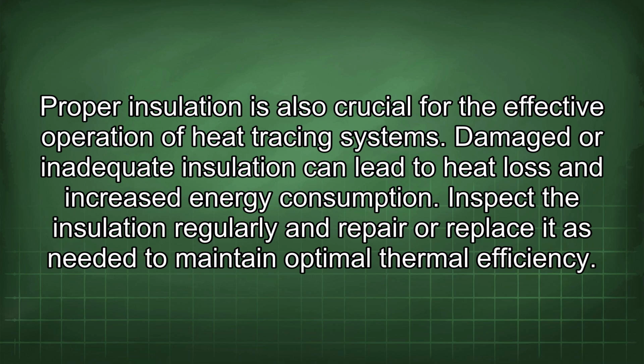Proper insulation is also crucial for the effective operation of heat tracing systems. Damaged or inadequate insulation can lead to heat loss and increased energy consumption. Inspect the insulation regularly and repair or replace it as needed to maintain optimal thermal efficiency.